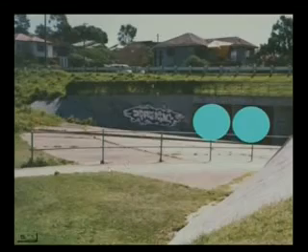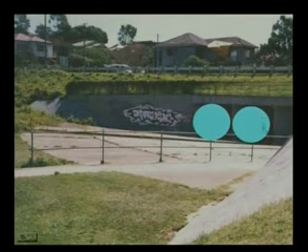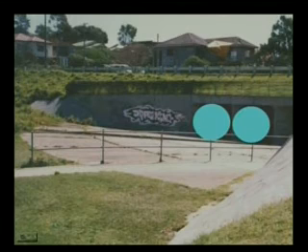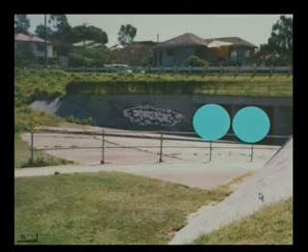In this particular problem, I have taken the thickness of the revetment as 300 mm. This figure I have picked up to show how a slope is. These are nothing but the vents. Through these vents, we can also provide pipes. This slope you can see here is filled with some granular material, and this is overlain or packed with a thick layer of stones. That is what we call revetment.